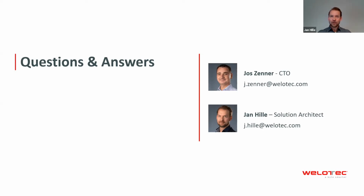Okay, we have a question from Ruben. He wants to know if the Edge Gateway 500 also provides a serial interface. The EG500 also supports and provides a serial interface. There's one serial port at the bottom, which can be either RS-232 or 485, software configurable. And with that interface, you can connect legacy devices and, for example, pull some kind of Modbus data or even have a transparent connection.